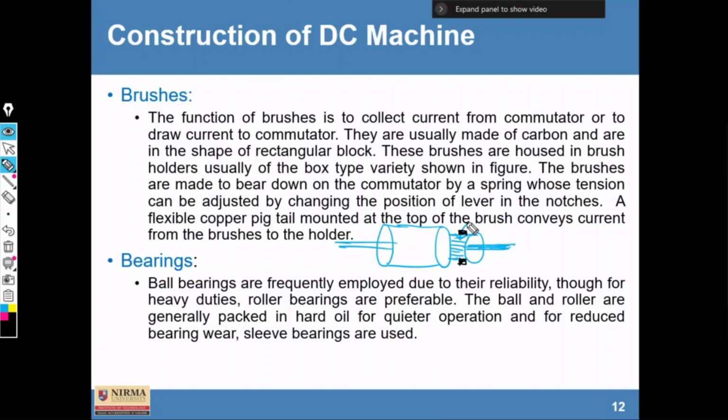And these carbon brushes are stationary and will not rotate, but obviously there is friction between the rotor and the brushes mounted on it. Through these brushes, by some arrangement, the rotating circuit is converted into a stationary circuit, and we can have electricity here. Right?